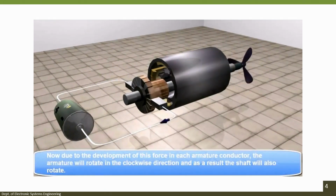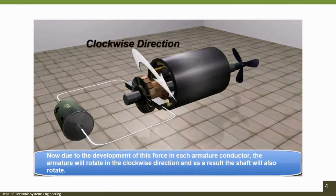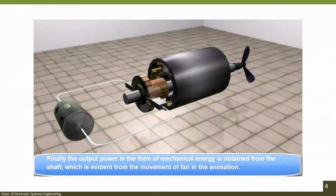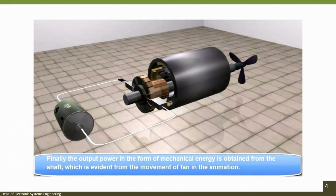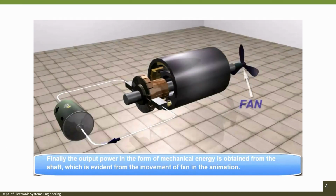Due to this force in each armature conductor, the armature will rotate in the clockwise direction, and as a result, the shaft will also rotate. Finally, the output power in the form of mechanical energy is obtained from the shaft, which is evident from the movement of the fan in the animation.